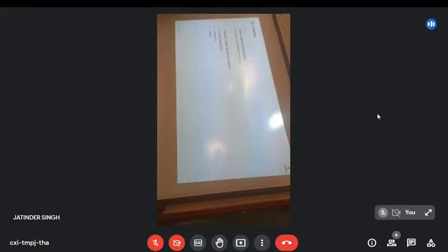With all these answers, it's then good to scribble down what the alternatives are. Are they equal? Are they better? Are they worse? Does it matter or not? If they're working in a chip with a 2 by 5 micron channel, and you can only make 500 micron channels, and you intend to repeat that work, you may want to understand if having that very small channel was critical to the results. If they use soft chip lines that you want to copy, or some kind of mixer, maybe not. If they use nanochannels to stretch DNA, it's probably not going to work in a very big channel.